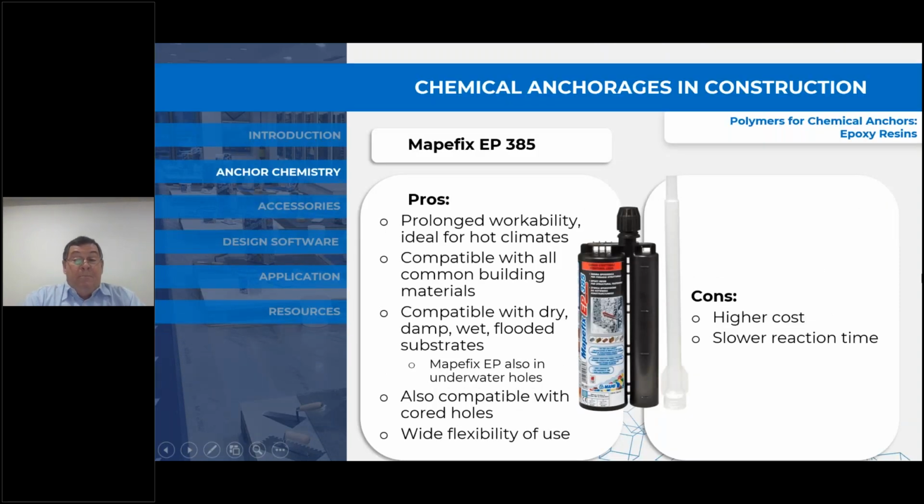We move to the epoxies, the 100% solids epoxy. Prolonged workability, ideal for hot climates because they have nice open time. Compatible with all the common building materials, compatible with dry, damp, wet, flooded substrates. They can be used underwater. They're also compatible with cored holes. There is no shrinkage whatsoever with the 100% solids epoxies, and subsequently they can be used in all these applications. The cons, I guess, are that they're a higher cost and the reaction time is much slower in the curing.